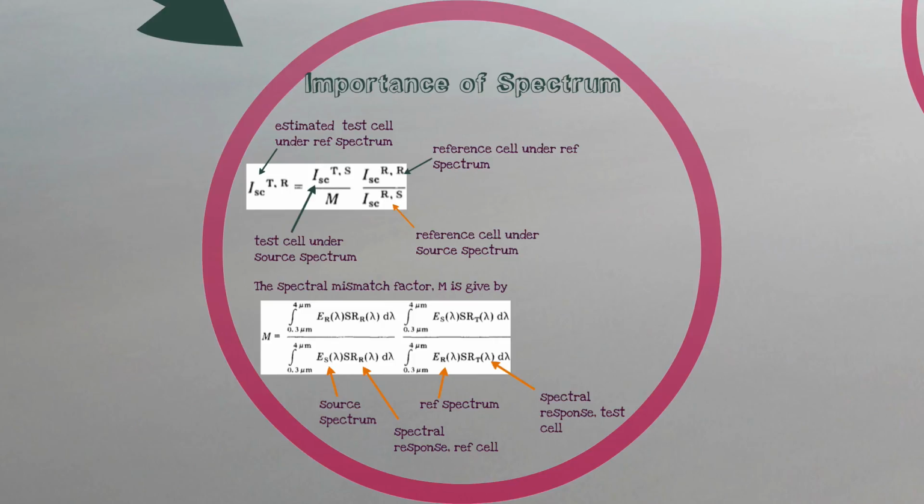Let's say I put a filter to adjust for the brightness, but because the spectrum itself is different. In other words, there might be more blue photons than green photons, for example, or more blue photons than red photons. And this shaping of the spectrum can also affect the response of the solar cell because there's a different probability for a given photon to generate an electron-hole pair in a semiconductor. And this we will come to is what's referred to as a quantum efficiency.